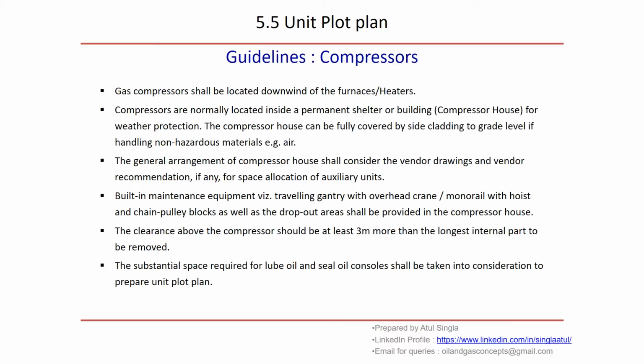So let us start with the guidelines for compressors: how we locate the compressor and what we need to take care of while finalizing the location in the plot plan. Compressors are located downwind of furnaces. As you know, furnaces and heaters are a source of ignition, so we keep these things downwind so that nothing is transferred to an ignition source.